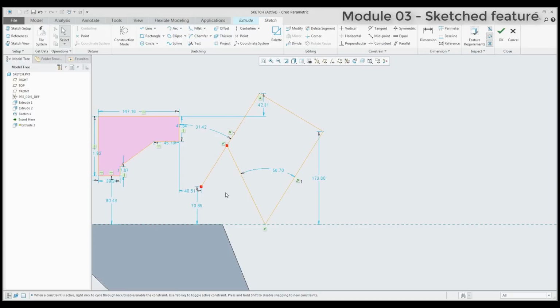And what about the lines here? Sometimes you need to move that point, this existing point, or you can create a corner. It's up to you. You can use the corner and the system will create a corner between selected lines, or I use this many times: I like to select the edge, hold the Control button, and move it. And you can see here the system automatically again creates a coincident for me, and the system will close the sketch.